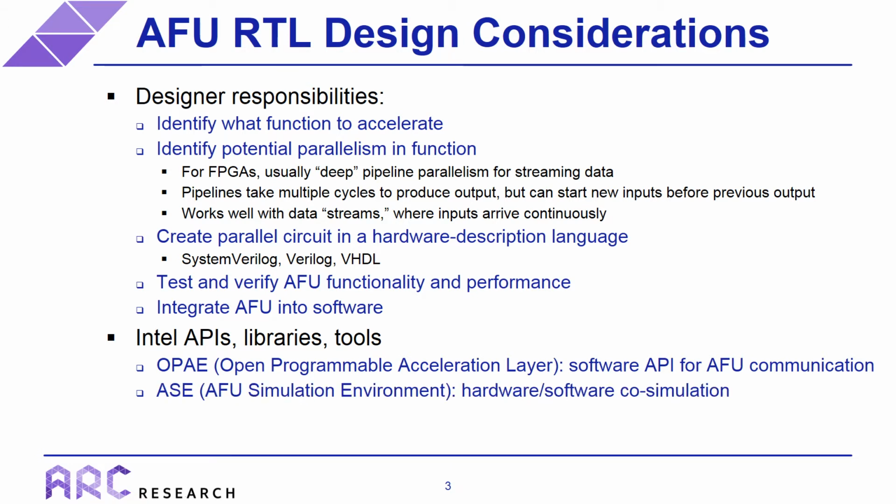Intel has this ASE or the AFU simulation environment. This is an incredibly useful environment that allows you to do hardware-software co-simulation. So once you have your register transfer level code, you need to be able to test it in simulation. Well, normally you would do that by creating a test bench, but creating a test bench in this environment would be very difficult because it has to mimic whatever the software is doing on the processor, and that would be an incredible amount of work to have to create that test bench. So what ASE does is it allows you to just execute your software code, and it communicates with the register transfer level code all within an RTL simulation.